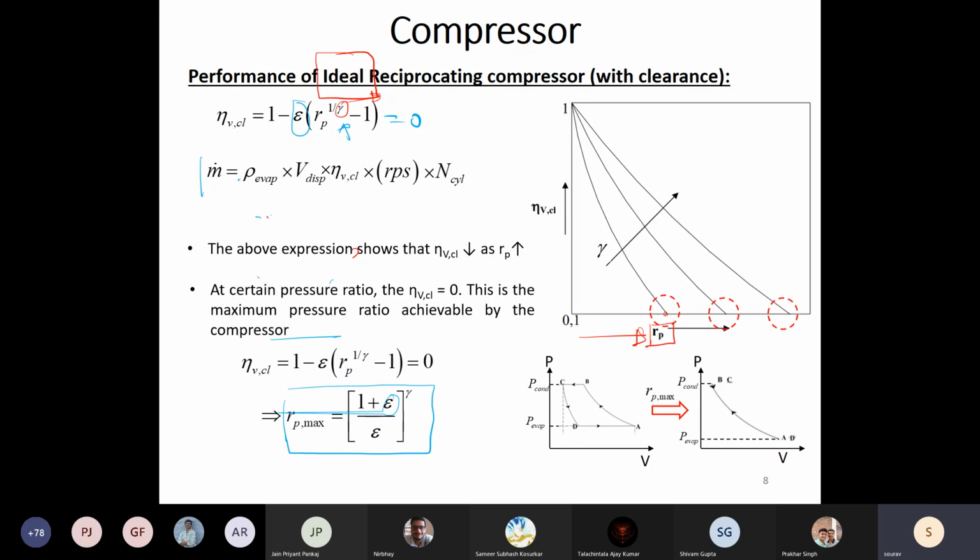They are trying to convey that the compressor used in this refrigeration system can deliver mass flow rate up to that maximum pressure ratio. And instead of giving you the pressure in terms of bars, which laymen will not understand, they are trying to convey some information about the condensing temperature.